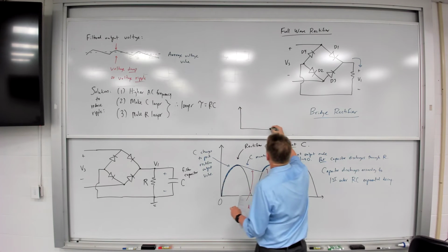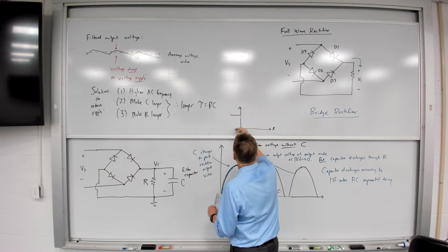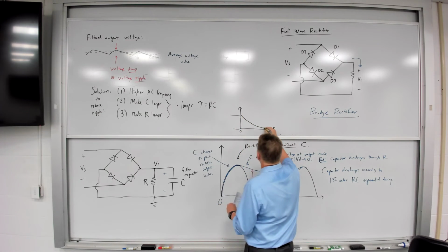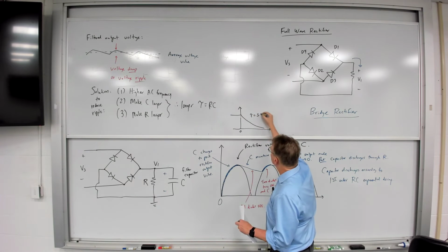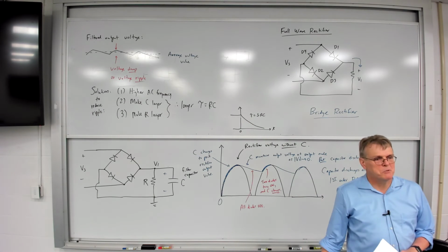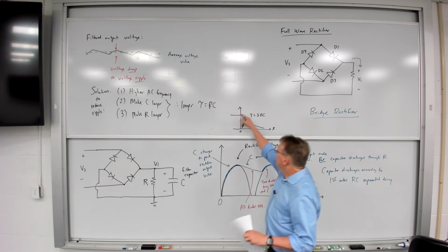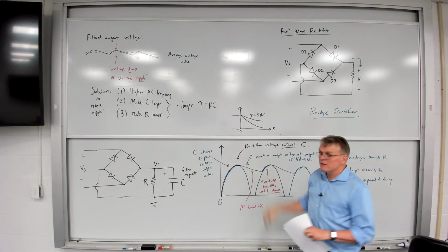The idea that if you charge up a capacitor to a particular voltage, it's going to decay away according to tau equals RC, with the full decay taking about 5 RC. Okay, first order response. So same thing here. If I make either R or C larger or both, then the slope of the decay gets shallower and shallower.